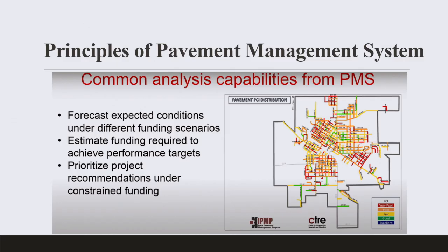What does this mean? This is not only talking about initial cost and initial design. It's talking about how much maintenance or preservation you can do along the years to a very large network of roadways or a very large network of bridges. If you have endless funding, you really don't need this. The golden rule is what? Any problem, treat it. But when you have 623,000 problems in 623,000 bridges, and the money is only enough for 1/3 of this, which one will you do first?